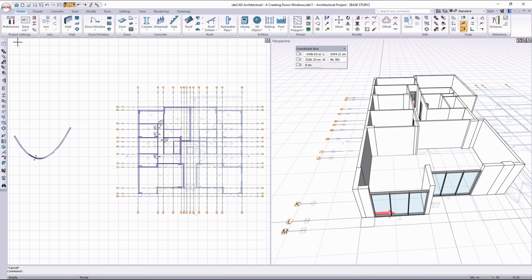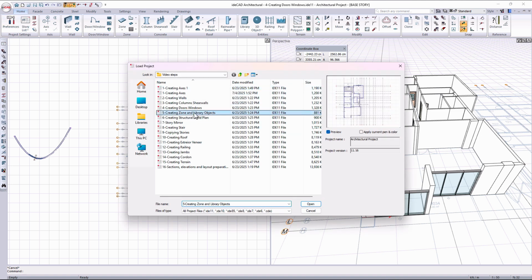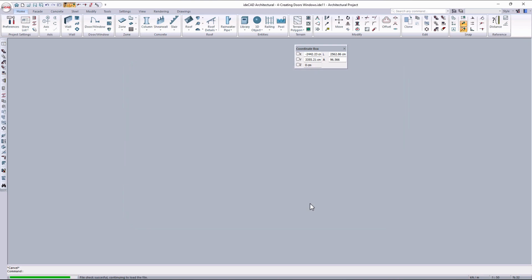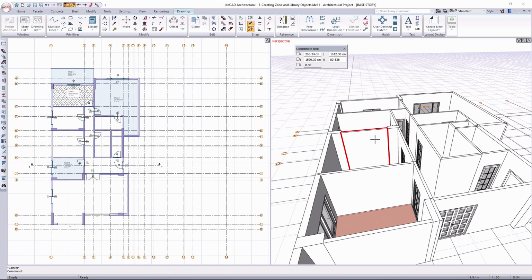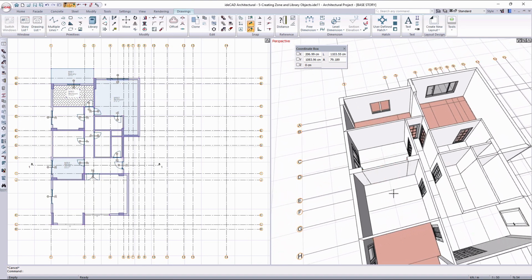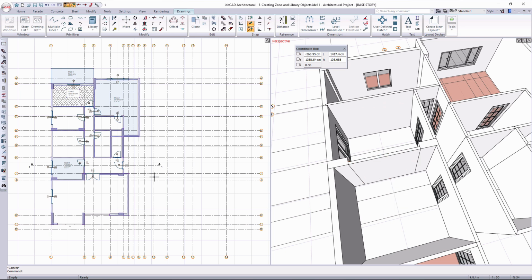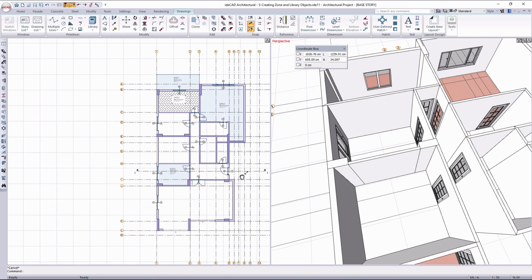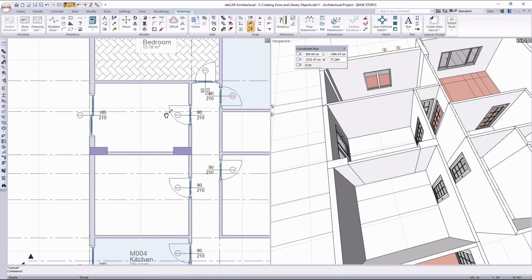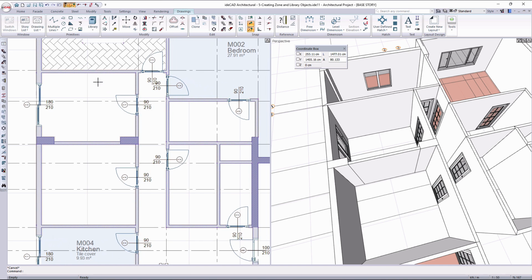We are now moving on to zone drawing. A zone is used to architecturally define a space and associate it with finishing and surface material information. It typically represents enclosed areas, such as rooms. To define a zone within a space, the area must be completely enclosed by elements like walls, columns, or shear walls.